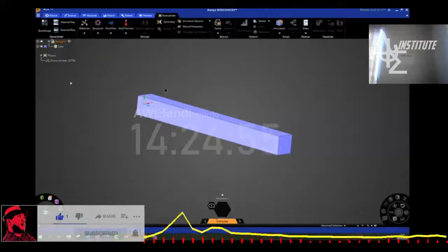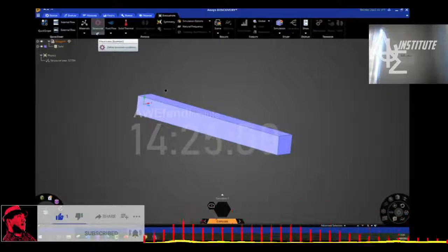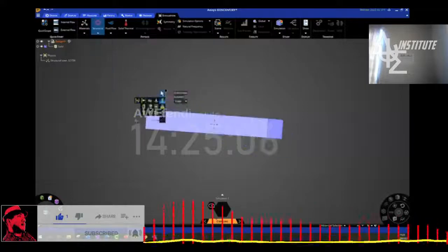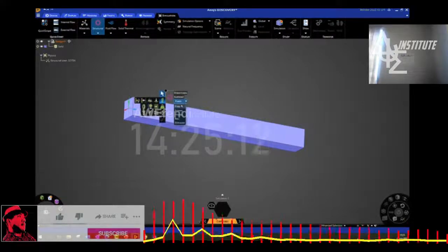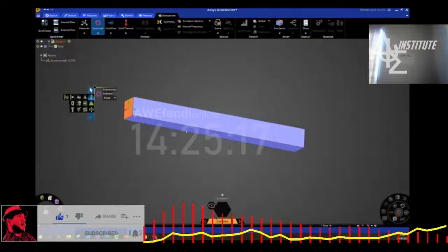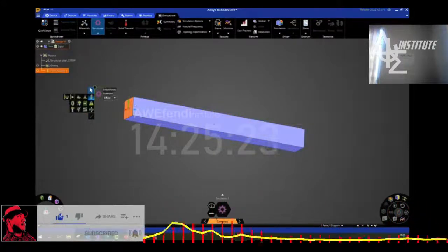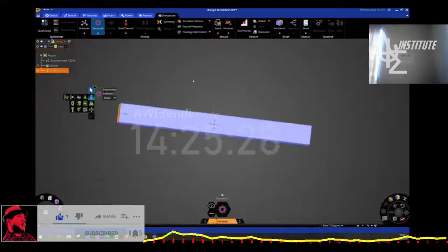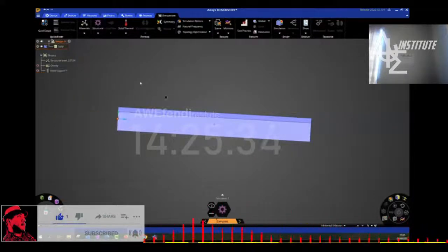So starting with the simulation tab, we go here. We know that we want a structural simulation, so I click the drop down and then I say support. Let me apply the fixed support on this end. You see different options over here. I know I want fixed, so I click on fixed and I select this face over here and I accept this. As soon as I did that, you can see that there is now a fixed support that has been added to our physics tree. So you know that your boundary condition has been applied. Again, to escape this tool, you click escape twice.